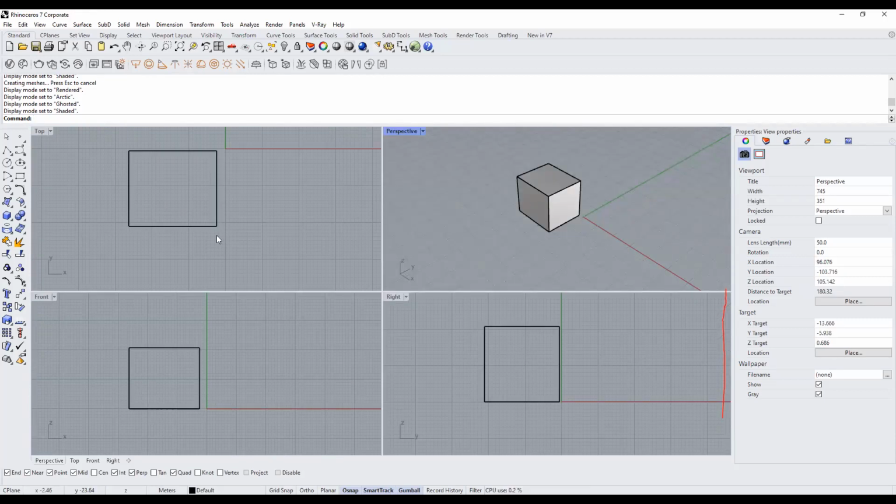Next, what we are going to see is how to access any tools in Rhino. Any tool that I will be accessing to teach in today's session, tools as in any action you want to do, like create a box, create a circle, create an array, any kind of command or tool you want to access, it's either going to be using the command box. If you're familiar with AutoCAD, this is going to be really comfortable for you guys.